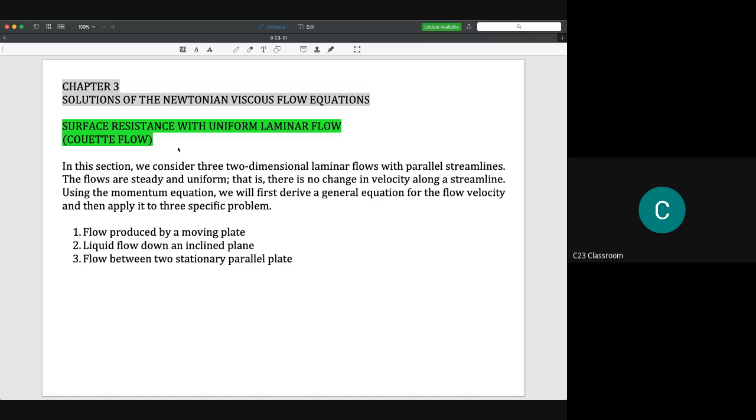Okay. So the difference is that the Couette flow doesn't have any difference in pressure. We assume that in Couette flow, the pressure remains atmospheric pressure all the time. So that is the difference. In simple words, the Couette flow is the flow between two plates. That's what we learned in the first chapter on viscosity, Newton's law of viscosity, tau equals mu du/dy. That's actually a part of the Couette flow. And the Poiseuille flow is the flow in a pipe.